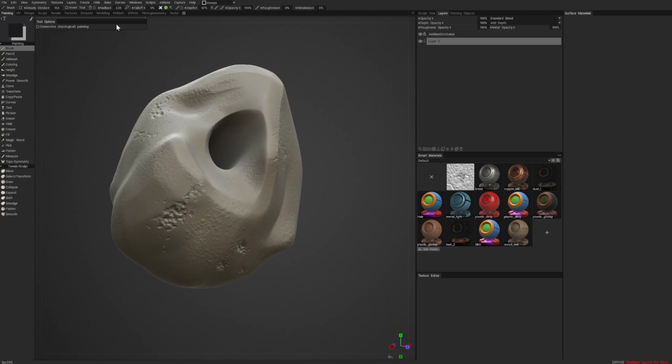And what I'm also going to do now is bake a curvature map. Again, you can adjust the light counts. You can go really high, but it's just going to take longer the more lights you have. So I try to not use the lowest value, but not too high. If you want higher quality results, you could crank those values higher and wait longer,